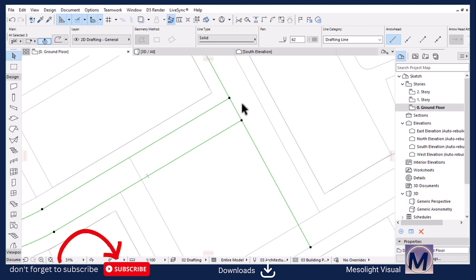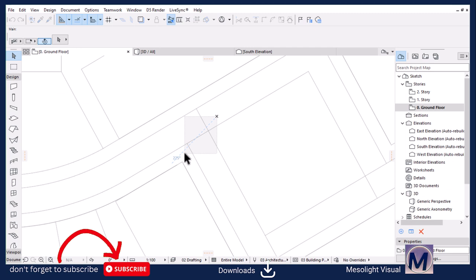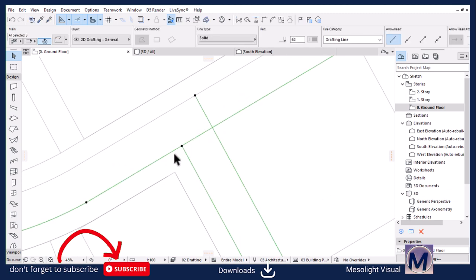To trim off, I'm going to hold control on your keyboard to activate the scissor cursor or scissor tool, and then I can just do that. But make sure you select the lines that you want to trim. You select both the line and then the lines that you want to trim using it, like this one.